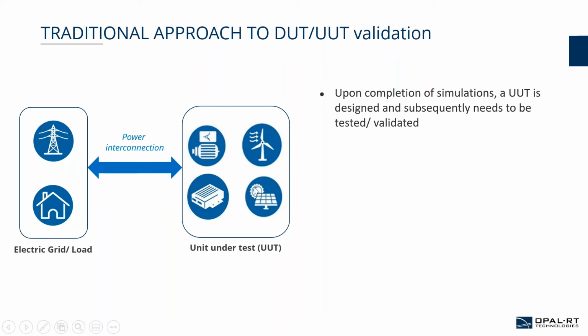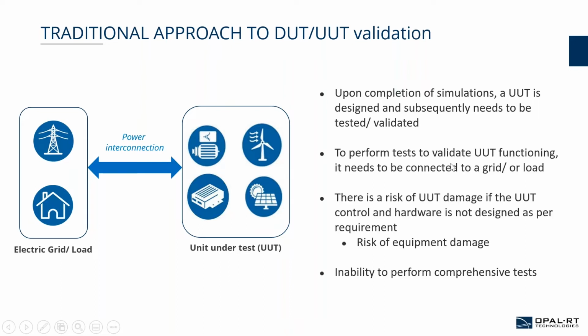It perhaps has a microgrid controller. It has controllers for the individual devices under test and so on. Typically, when you want to test this equipment, you would eventually connect it to the grid because you want to see if your MPPT algorithm is working as it should. You would want to verify if the microgrid controller, which essentially shares power between the two resources when it comes to grid integration, works as it should, and so on.